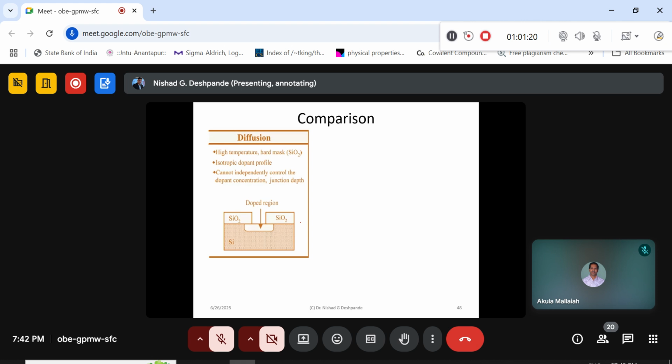No, now see, this is a different process we are discussing. Earlier we were talking about the wet process and dry processes, right? That is where we were trying to develop this particular oxide layer here. Now we are not talking about these layers. Now we have a channel, and we want to have a different kind of conductivity, either n type or p type. I want to make a different region here. In that case I am talking about the diffusion process. Now I talked about the thermal diffusion process.